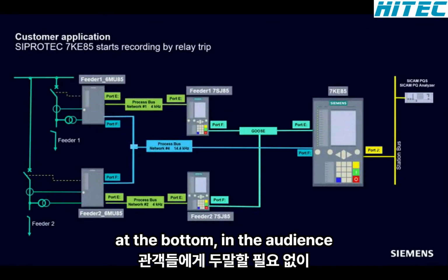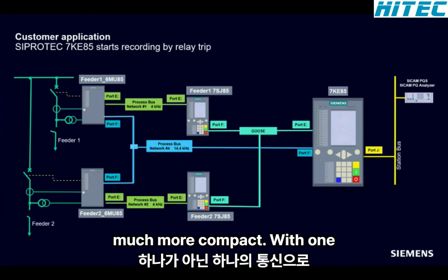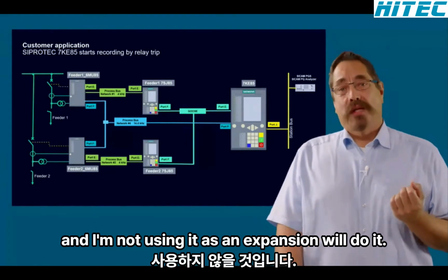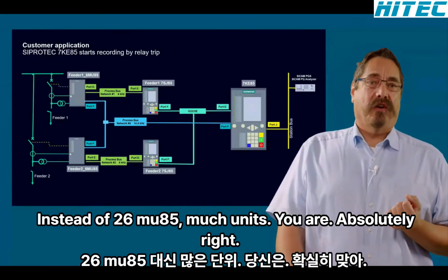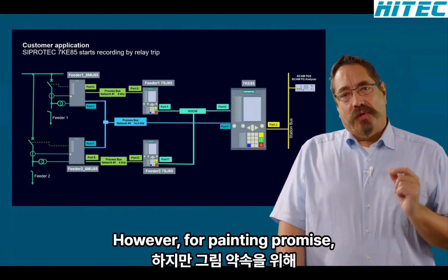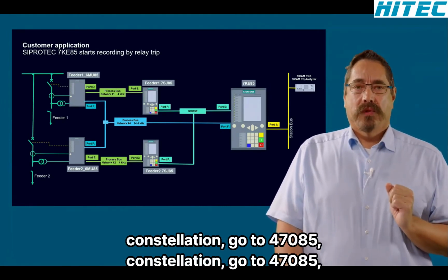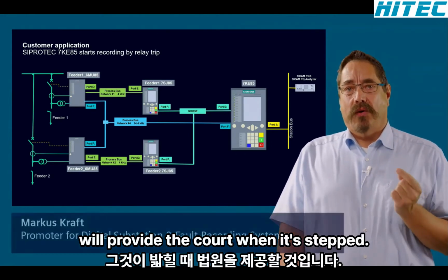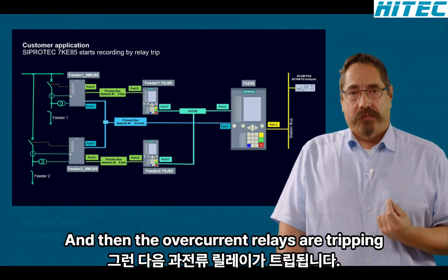The experts in the audience will now say, hey Marcus, what you are showing right now can be realized much more compact, with 1 instead of 2 communication modules and a merging unit with an expansion module instead of 2 6MU85 merging units. You are absolutely right. However, for training purposes, I decided to set it up in that hardware constellation. Good so far. 7KE85 will provide the fault records when its own trigger limits are overstepped and when the overcurrent relays are tripping.